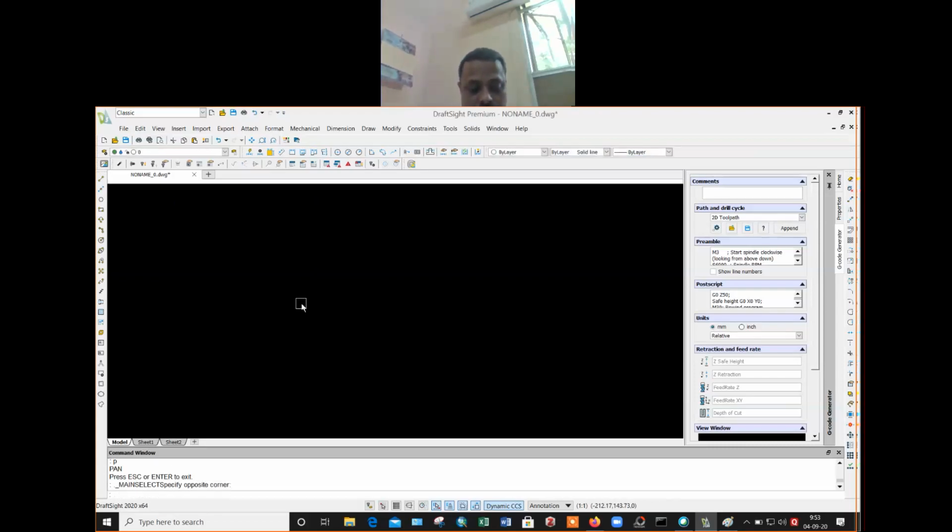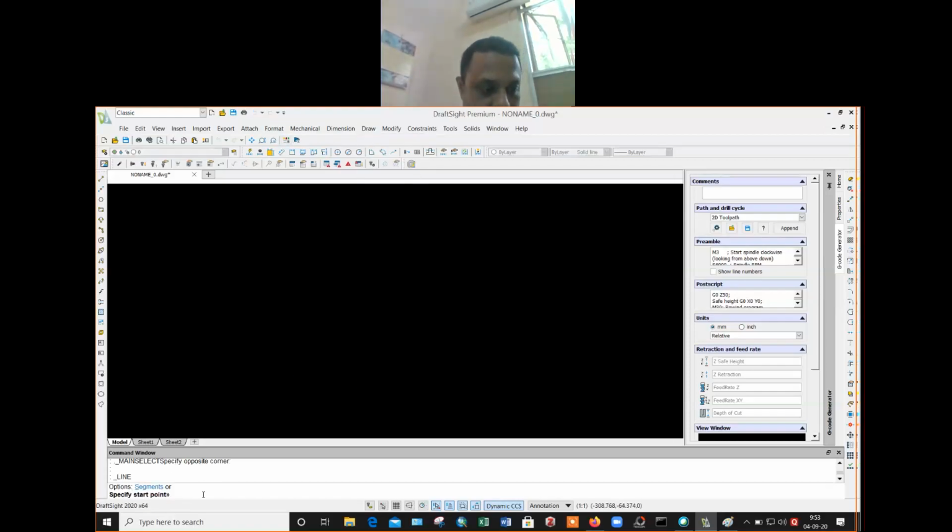So what will I do? I will go to draw line. Specify start point. My start point is 0,0. Then how much should I go this way?